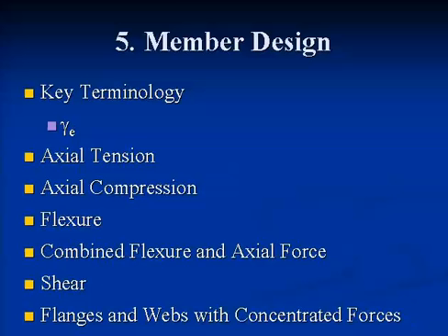With a tapered member, even with a constant force through the member, the stress is always varying. So the way George Lee dealt with it is to say pick an end of the member and look at the stress at that point. We look at gamma E, which is the multiplier of the loads, no matter what kind of pattern they're in, compared with the elastic buckling condition of the member. Don may be getting into it, I don't know. It's something that you're going to use.